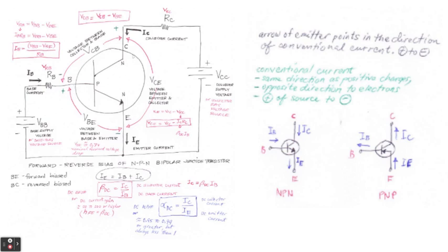Now, on the collector side, you will see that this is N-type connected to positive. So this is N-type, which means that the majority of the charge carriers are electrons. So if you connect it to a positive source, then it will be in reverse bias. And precisely that's what we mean. We need to connect the base to the positive and the collector to the positive, so that we will have forward bias on the left side or the input side, and we will make it reverse biased in the output side here on the right.